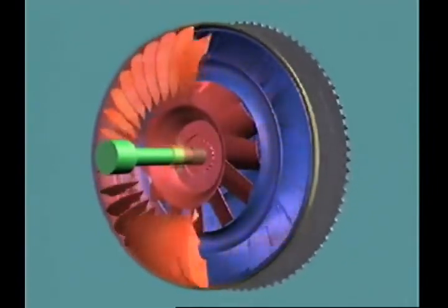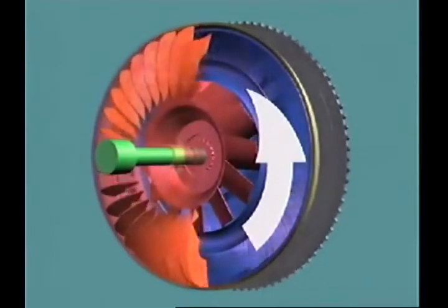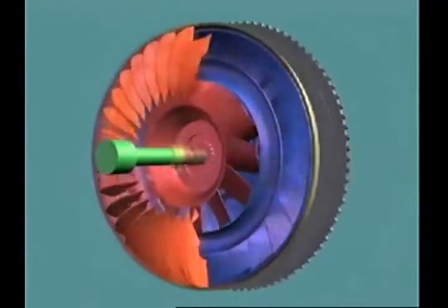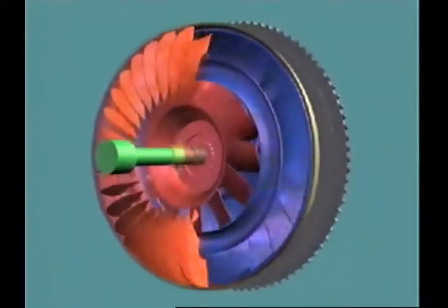At coupling point, fluid flow from the turbine vanes is relatively low, but it is at high speed in the direction of rotation. The rapidly turning turbine discharges its fluid against the back of the stator blades. This force unlocks the stator and all three elements rotate as one unit. Unlocking the stator prevents turbulence in the fluid and any braking effect on the engine.